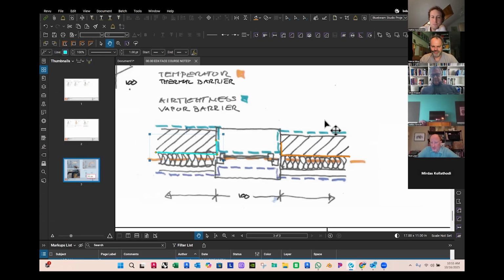So the question I have though is that I'm still confused because what you're telling me is this line right here. Could that line there, you're saying could be essentially here, right? No, in the material itself, not in the middle of it, let's say. Exactly. Yeah, like that. Like this, yes. Yep. And then the material itself, the solid wall, acts as a vapor barrier.